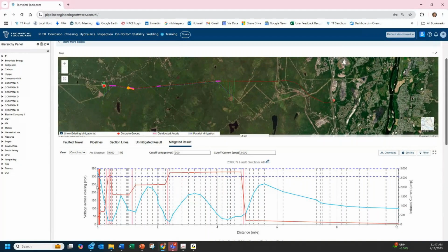Our maximum voltage is, here's your 300 volts right here, and we are about 326 volts. And then the fault current is around 2786. Let's just say about 2800 amps. So we could look at this rather quickly, and if you notice the amps are up, the voltage is down. Okay, so keep that in mind. That's based on the way the circuits are run.